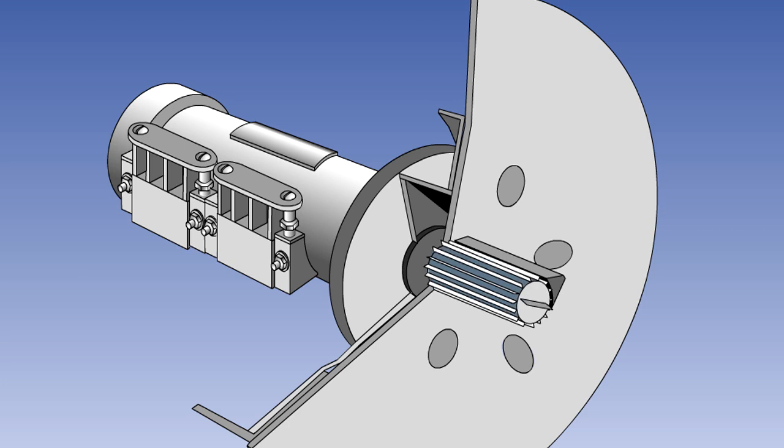The unit is mounted on flexible mountings on the side of the aircraft fuselage, with the rotor shaft protruding into the airflow with its axis at right angles to the airflow. The cutter is in the lee of the shaft. Under normal conditions, little torque is required to drive the rotor.